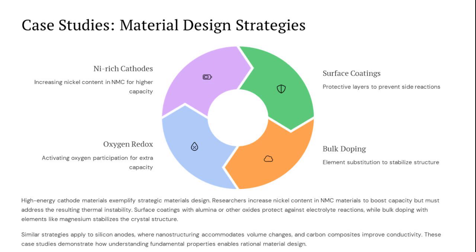Silicon-based anodes. Silicon anodes are being investigated by the Silicon Anode Consortium as a possible viable alternative to graphite due to their much higher theoretical capacity. However, they face challenges related to volume expansion during cycling. Fast ion conducting solid electrolytes: research has demonstrated that high ionic conductivity exceeding that of liquid organic electrolytes can be achieved in non-oxide inorganic solids. These materials are enabling the development of all solid-state batteries.